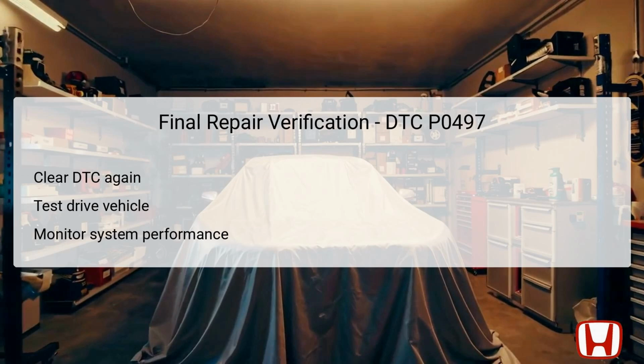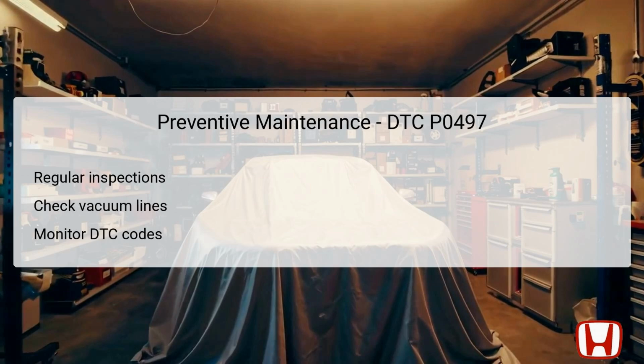During the drive, monitor the EVAP system's performance, paying attention to any signs of hesitation, performance dips, or the check engine light turning on. This step confirms that the issue has been successfully resolved and that the EVAP system is functional. Ensuring each component is performing correctly is crucial in maintaining compliance with emission standards and ensuring the longevity of the vehicle. Preventive maintenance is key to avoiding future occurrences of DTC P0497.